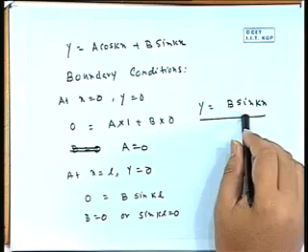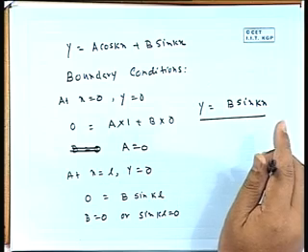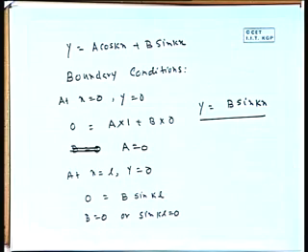Now there B is not equal to 0 and y equal to B sin kx is there. So the equation of the curve is B sin kx. So it will follow a sinusoidal curve having an amplitude B, and it will be 0 at x equal to 0 and 0 at the other end. So at critical range, if we give some displacement, it will take a sinusoidal form. So if we give B as 1 centimeter, with a 1 centimeter amplitude we will get the deflected curve.